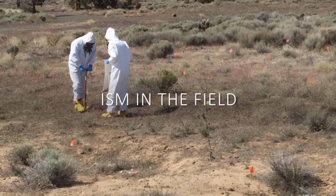We quickly learned that although the area seemed to be homogeneous before we started sampling, it varied in distinct patterns across the site. Some specific areas were sandier than others, some had a more clay-type soil. This type of familiarity with the site could become useful in understanding the fate and transport of contaminants across the area, or could explain unexpected heterogeneity between the samples. But you would otherwise not have this intimate knowledge of the soil in your area if you were not collecting such high density increments throughout the decision unit.